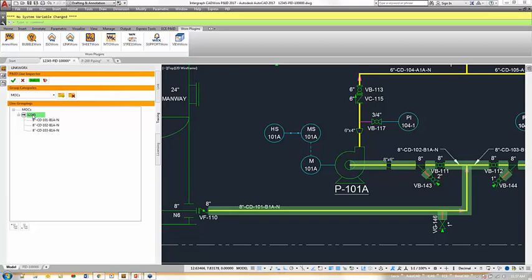Very good question. Right now I'm live in the P&ID, but this application is also reaching through as an XREF. So I can create a new drawing, bring in the P&ID as an XREF, and accomplish the exact same task. That holds true not only for the P&IDs, but the 3D models as well. So if you elect not to carry your tracing in the native P&ID, it can all be done through creation of a drawing and XREFing the P&IDs.